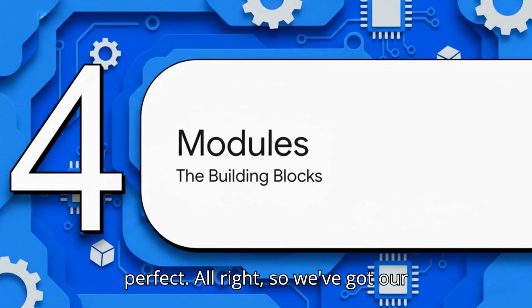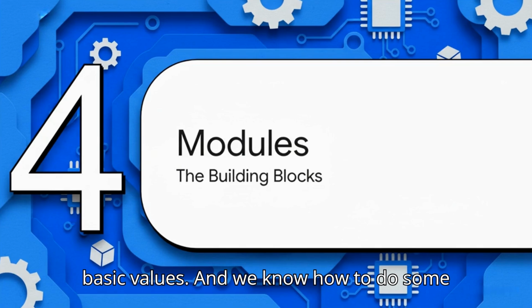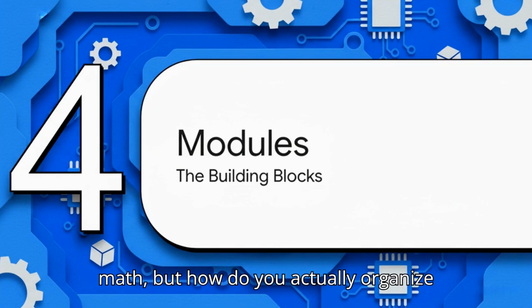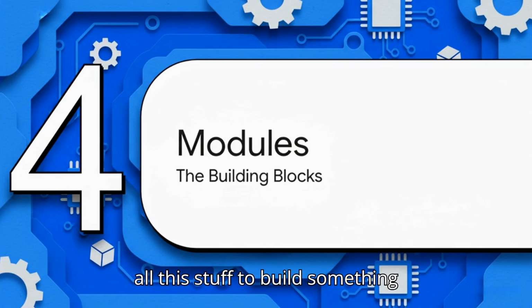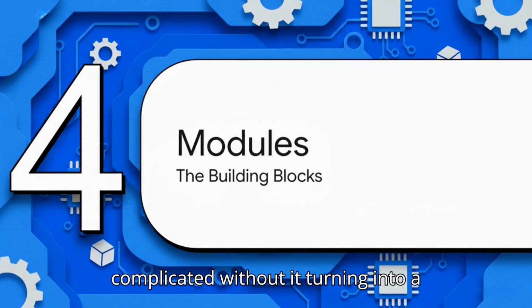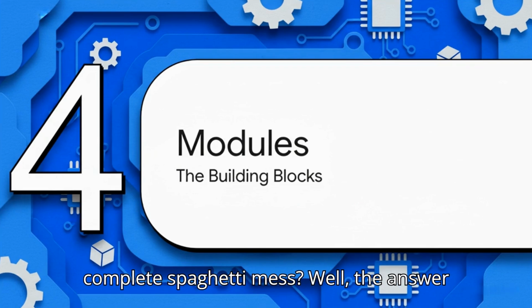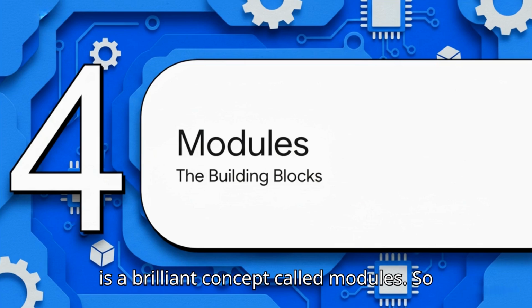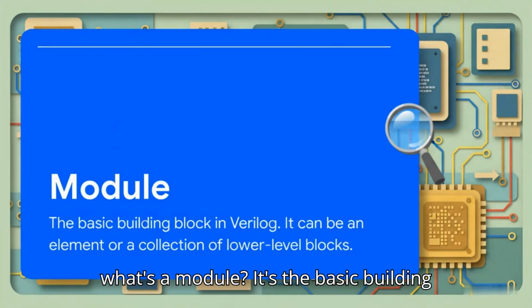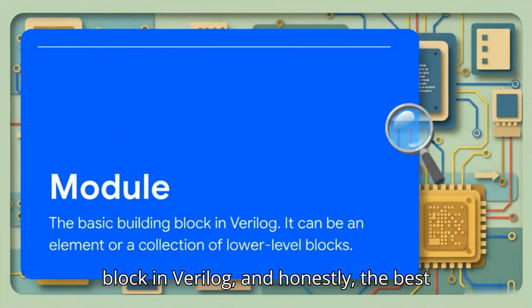All right, so we've got our basic values and we know how to do some math, but how do you actually organize all this stuff to build something complicated without it turning into a complete spaghetti mess? Well, the answer is a brilliant concept called modules. So what's a module? It's the basic building block in Verilog.